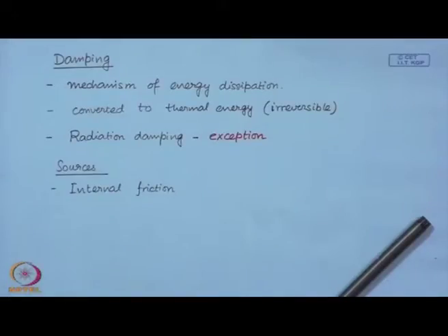Now, one thing to note is we are considering one dimensional structures. There is no question of any layer in a one dimensional structure, but we are going to have a phenomenological model based on the rates of stretching, for example, of the structure, the rate of strain. So, strain rate, to model internal friction or internal dissipation.